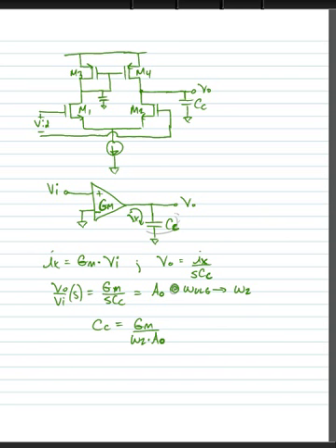Okay, so these are a couple of techniques that we use that are narrowbanding techniques. In other words, what we're trying to do is make the dominant pole so dominant in this circuit that it separates itself from the higher frequency poles and allows us to use the op amp in a stable configuration up to some higher frequencies. But this is a fairly inefficient technique.